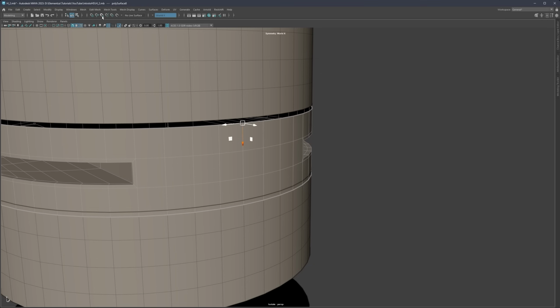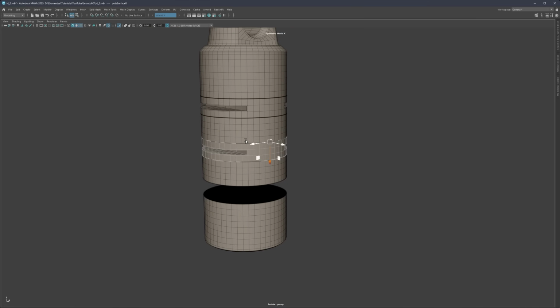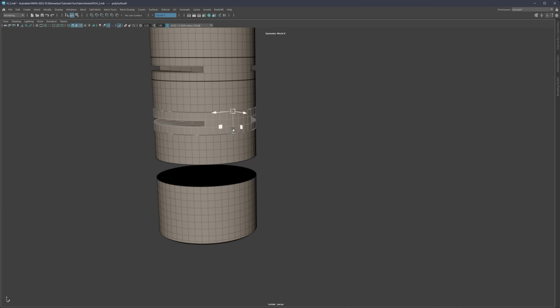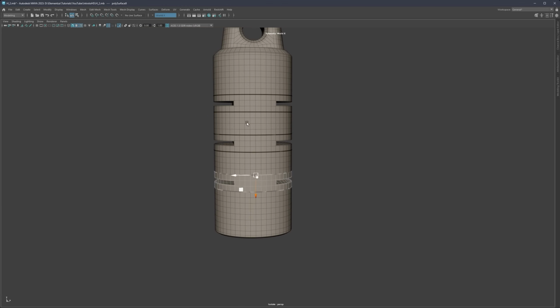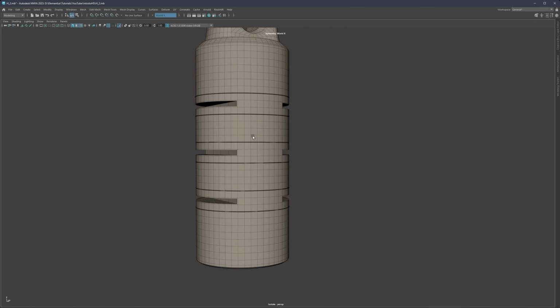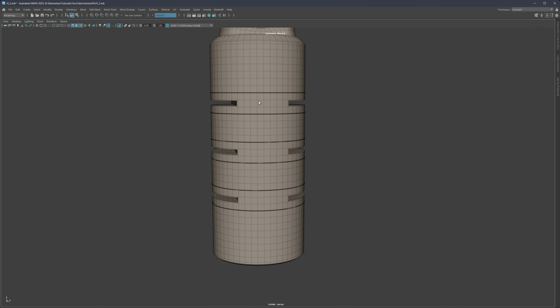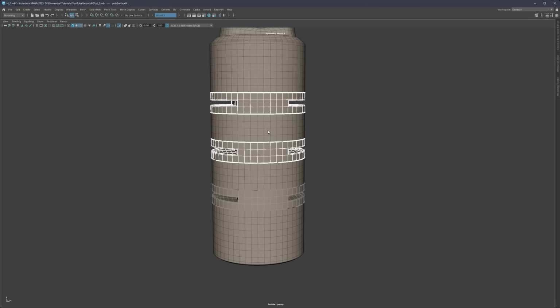And if you remember, we have snapping enabled with V. And if you hold V, you will just be able to snap here on the top. And if you go to, again, shift, clone, now we can just repeat the same operation and snap it right here. So now we have a quick solution here, and just skipped all that dirty part. And now the only thing that we need to do is stitch it all back together. The problem is that now we have 1, 2, 3, 4, 5 pieces.